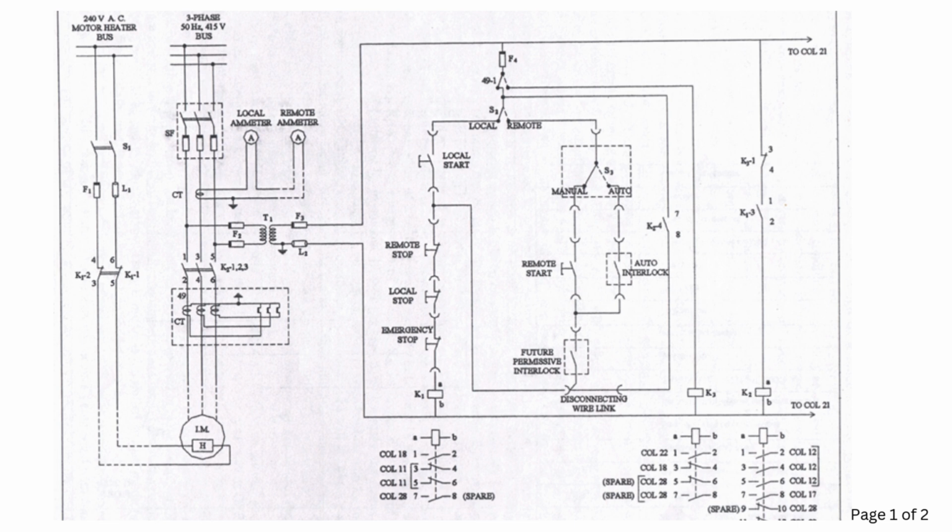So it means when your motor is in running condition, there is no need to keep the space heater on. You can turn off the space heater. Normally, it is turned off automatically by some interconnection or interlocking mechanisms. The induction motor is connected to the 415-volt three-phase AC supply through a switch fuse unit, you can see here, and the contactor, the contacts of the K2 contactor.